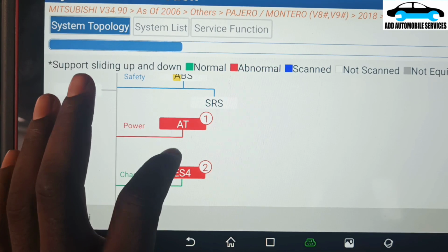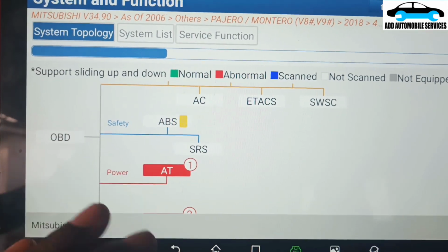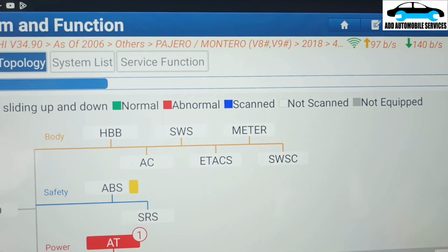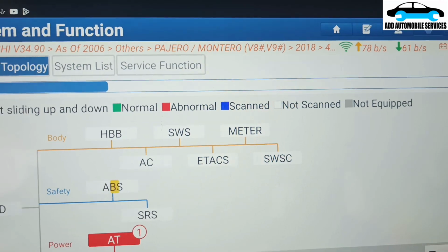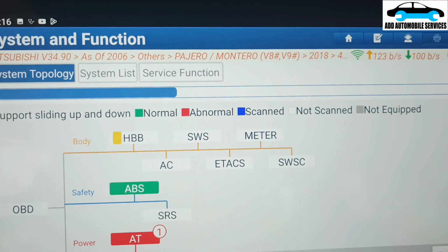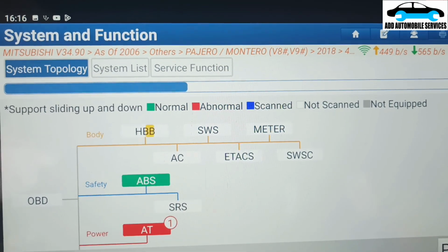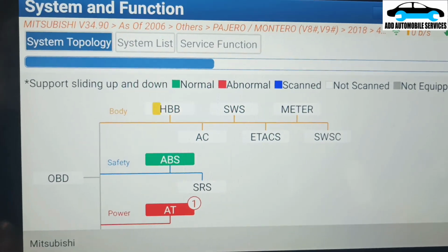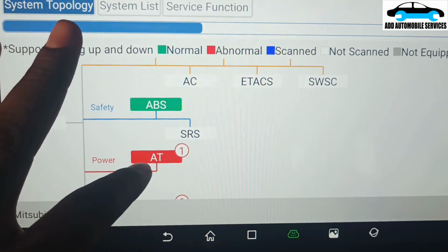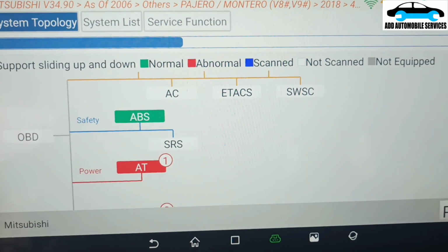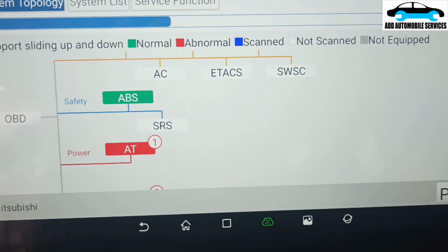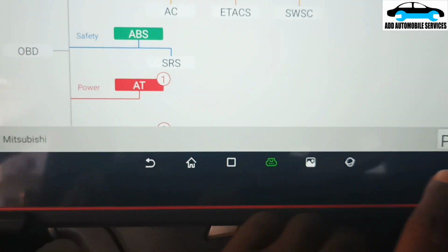So this is the T80 automatic transmission that is being used, because the engine is a mechanical engine, so it doesn't need any control board that much. They've added the little control parts that the vehicle will need, like engine speed and throttle position, for the gearbox to change properly. All of them are needed, and it has been added to the T80. So if there is any electrical fault with the system, it will go to the T80. Let me pause it.